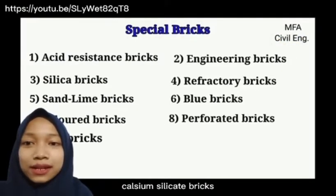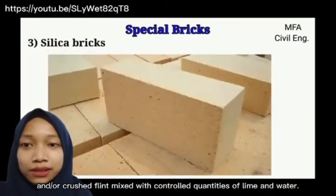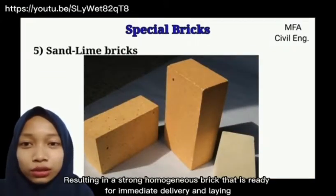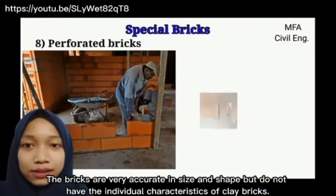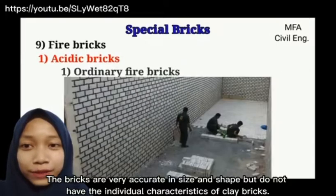Calcium silicate bricks. These bricks are made from carefully selected clean sand and/or crushed flint mixed with controlled quantities of lime and water, resulting in a strong homogeneous brick that is ready for immediate delivery and laying. The bricks are very accurate in size and shape but don't have the individual characteristic of clay bricks.